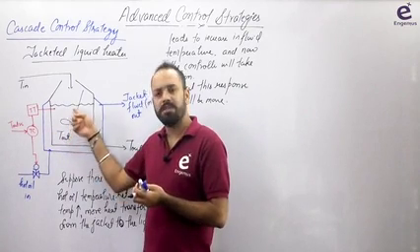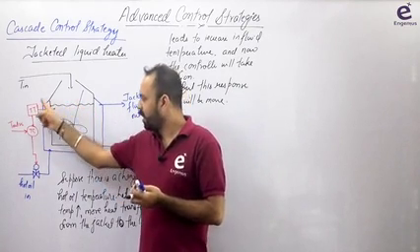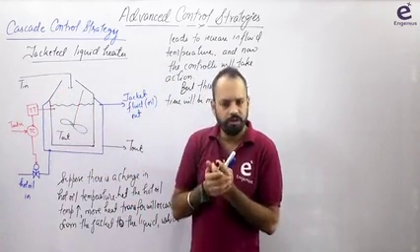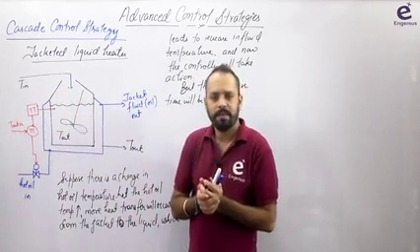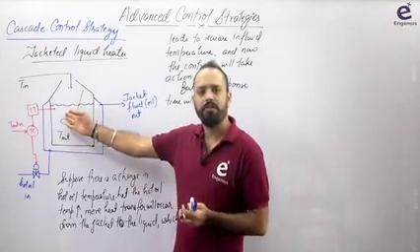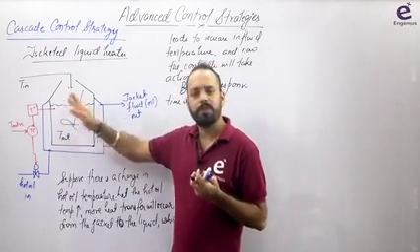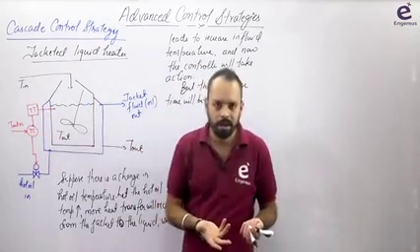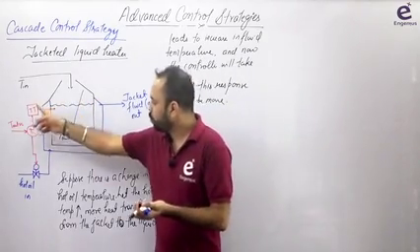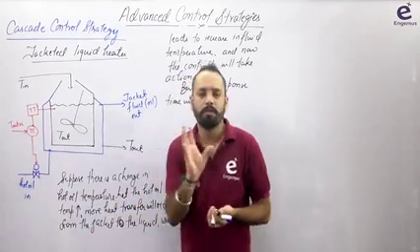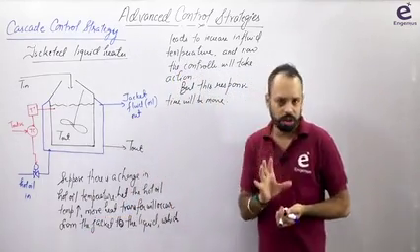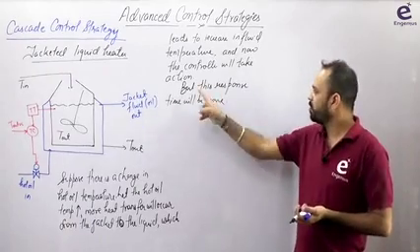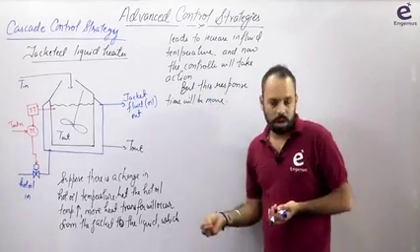Now as this temperature changes gradually, suppose this temperature transmitter has some lag in measurement, it is not very fast, it is not instantaneous, then for a longer period of time this temperature will remain away from this set point. It does not know, right? When you do not tell it, how will it take action? So this transmitter is going to tell this controller and then it will take action. So what is the problem? The problem with conventional feedback control, not always in these kinds of problems, is that the response time will be more, and